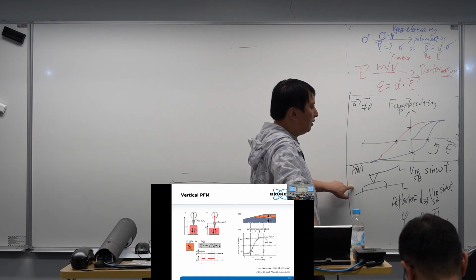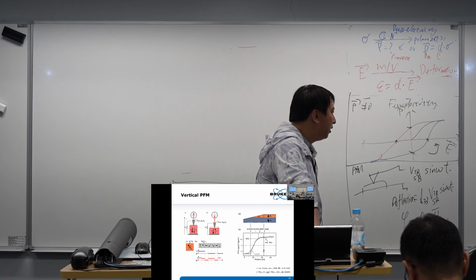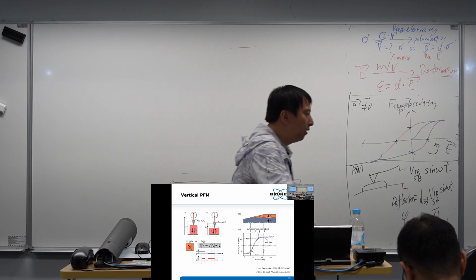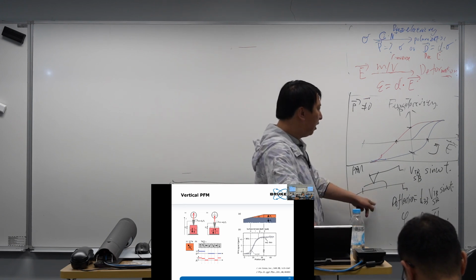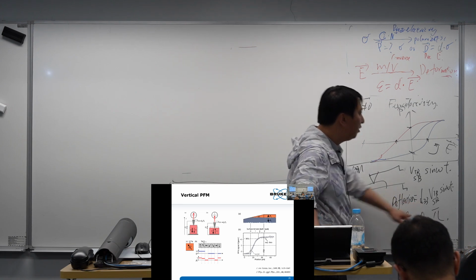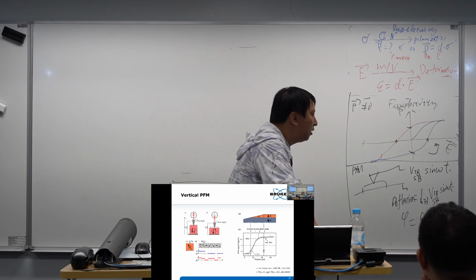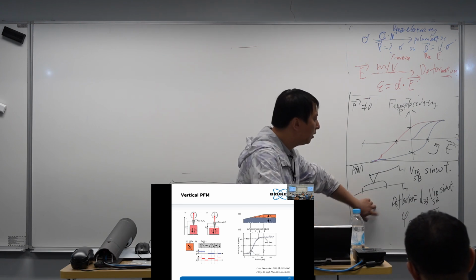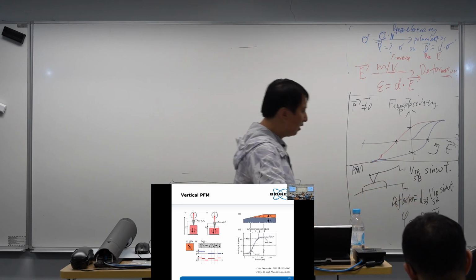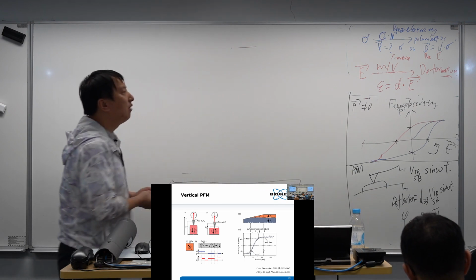We get it modulated with an AC field. So we apply voltage at a certain frequency, and then our deflection will be proportional to d33 and this frequency term. Then the amplitude directly gives the d33, and the phase can be 0 or pi. That's our theory, right?